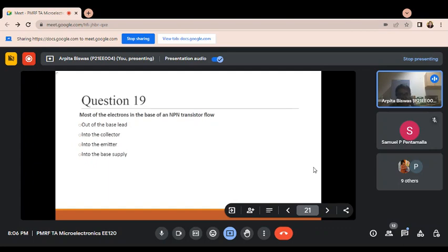As the reverse bias voltage is increased, the junction width becomes wider, so the effective base region decreases, so the electron can easily move from the emitter through the base to the collector. Also, the collector has a positive charge, so it attracts the electrons towards the collector. So now it is clear.